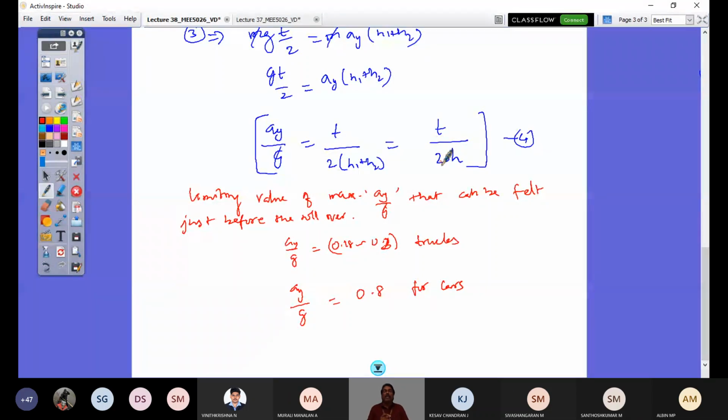Then there will be a chance that the vehicle rollover takes place. Otherwise, if there is no hit of another vehicle on one vehicle, the rollover in race cars is not that pronounced. Rather, it would be spinning about the vertical axis. Anytime the stability of your racing car is lost, by observation you can see that it spins about the vertical axis, right? Whereas trucks roll over when they fail to hold their stable state.